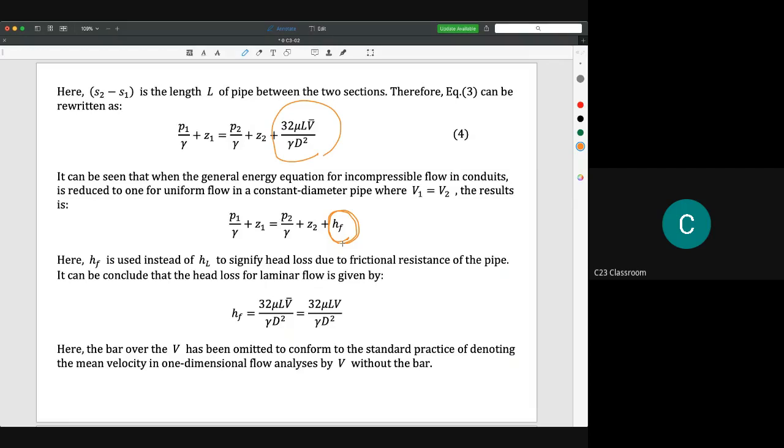One of those equations, the losses, actually comes from the idea of Poiseuille flow. You start from a small element that you take from the flow in the pipe, calculate all the forces that interact with that element, and finally you get the total flow rate. You calculate the average velocity, and then you find that it gives you an extra term.